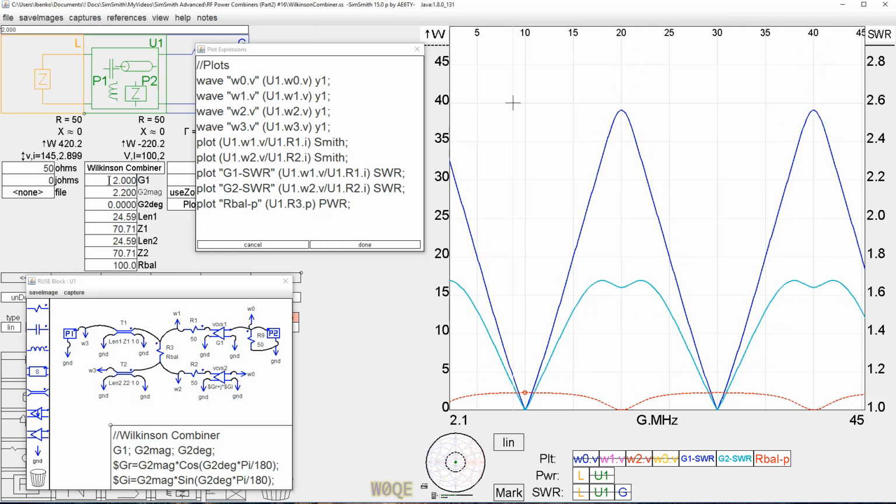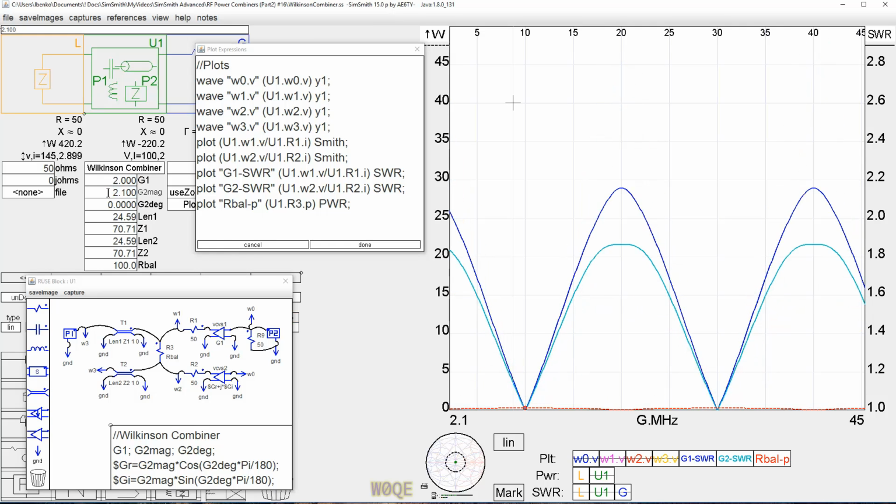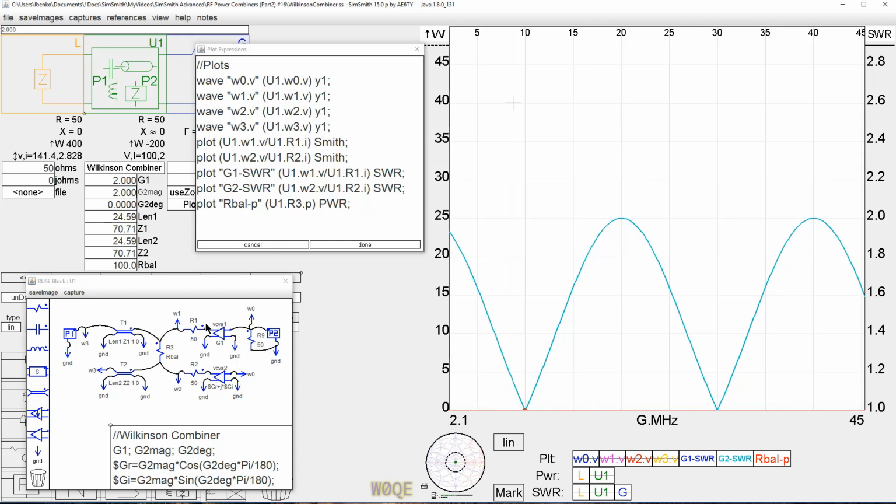So that tells me that you really don't need two precise generators here. You need to pay some attention to get the phases right, and you don't want to have this generator drive the power combiner through 20 feet of transmission line, and this one drive it through 0 feet of transmission line, or something like that. But if you exercise reasonable care, the phase will be close enough. The amplitudes aren't that important. It acts as a very nice power combiner, which is its goal.